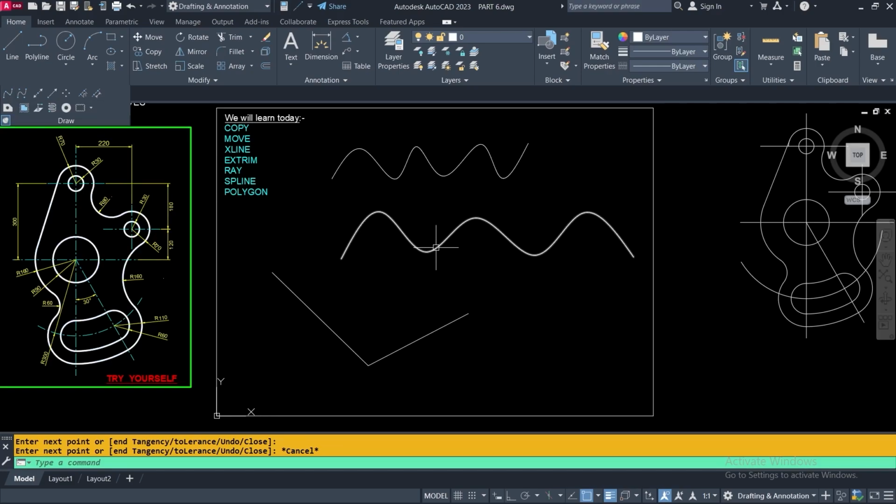Okay, now, this one, SPLINE fit, we have used. I am selecting this by mouse click. You see these grips are showing, and we can edit this SPLINE through these grips. See here, I am moving my cursor on those grips. I am moving my cursor on this blue grip. When the cursor is placed properly, it is light red. I am clicking on it. Now it is deep red. I can move, I can edit this point. Now if I click here, it will be here.